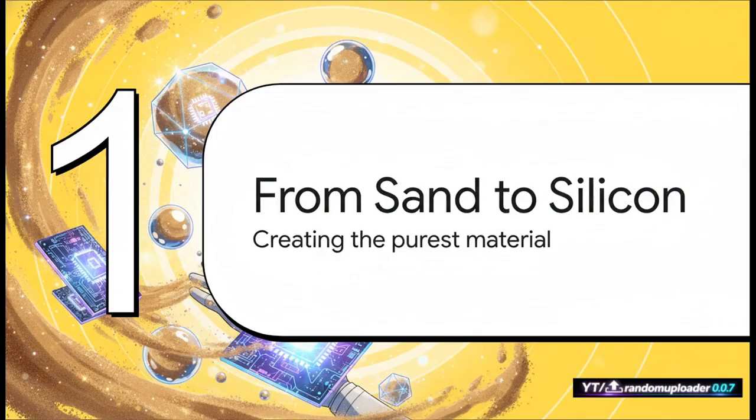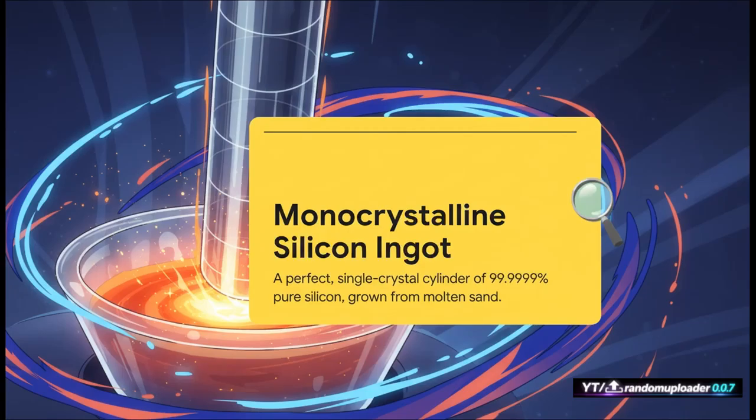Okay, so our journey begins with the very first, and maybe one of the most critical transformations, turning that raw sand into a material that's almost perfectly pure. The whole process starts by melting down purified sand in something called a crucible. From that molten silicon, a huge, perfectly structured single crystal is slowly, carefully grown. The result is this, a monocrystalline silicon ingot. And get this, it's 99.99999% pure, which makes it one of the purest materials we have ever made.